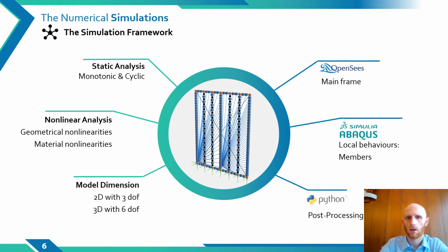The analyses were performed through a static procedure taking into account the geometrical and material non-linearities. We created 2D and 3D models using the OpenSees software, as well as I used Abaqus for component characterization, such as the member response.